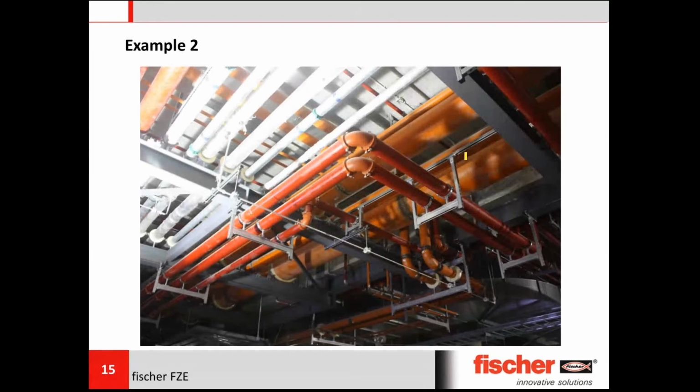So in between, we provide a secondary steel slotted channel, as you can see here, and from this slotted channel we drop the support. So sometimes things are not very simple, so we have to do custom engineering solutions, which we are known to be best at.